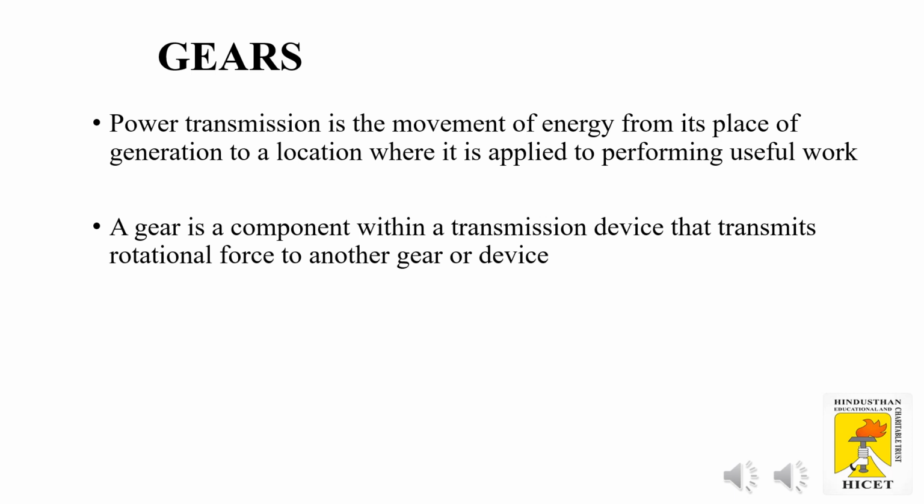When the pinion is the driver, it results in a step down drive in which the output speed decreases and the torque increases. On the other hand, when the gear is the driver, it results in a step up drive in which the output speed increases and the torque decreases.